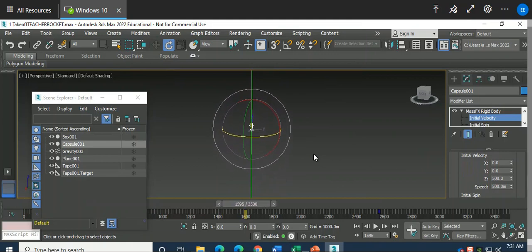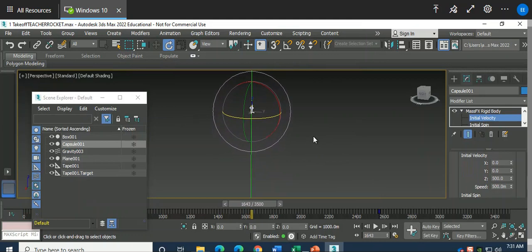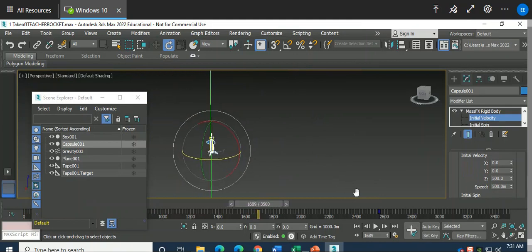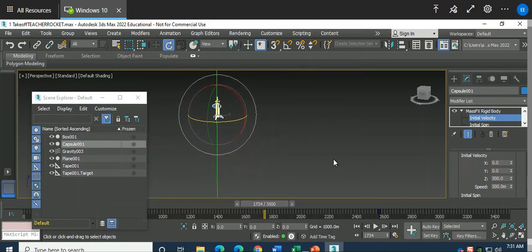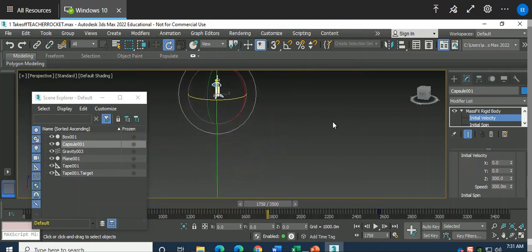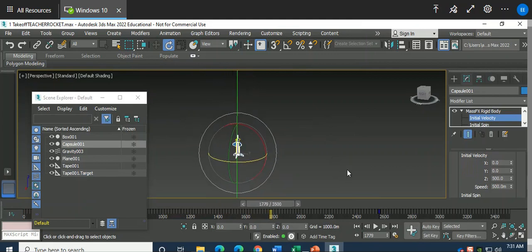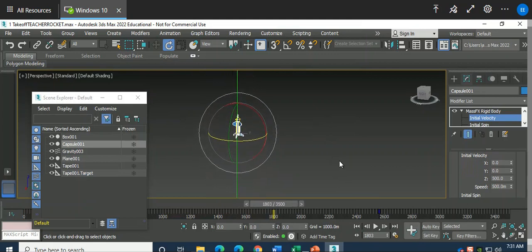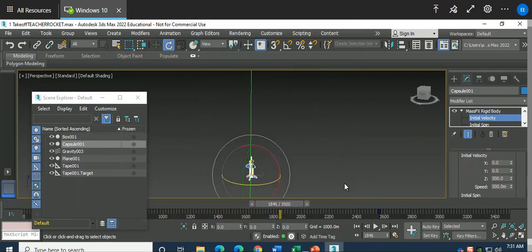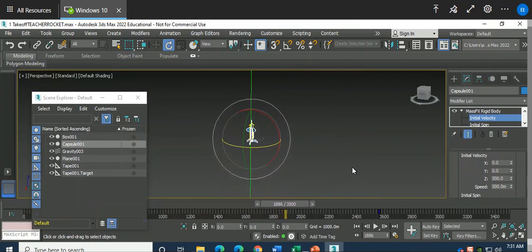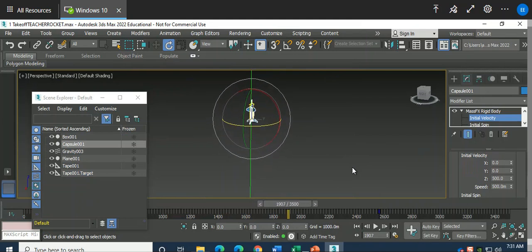At the bottom, there is a slide rule that shows the number of frames in the simulation. Right now it's 1600, 1700 frames, and I originally set it up to 3500 frames. The number of frames per second is approximately 15 frames per second. So you can also calculate how many seconds it took for the rocket to ascend by just dividing that final number by 15.